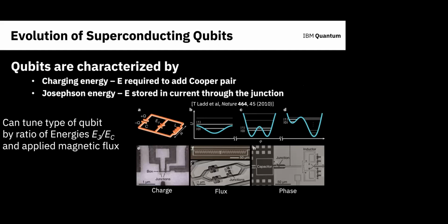It also depends on the magnetic field going through that loop for some very specific reasons. So your overall magnetic field will give you an overall global phase difference. And then across these junctions here, there can be phase jumps as well. Those phase jumps determine the critical current passing through those junctions. So all these things are related.